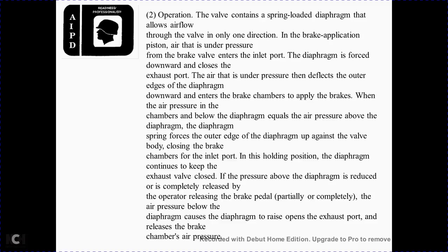Brake chamber to apply the brake. When the air pressure in the chamber below the diaphragm equals the air pressure above the diaphragm, the spring force on the outer edge of the diaphragm closes the valve with the body, closing the inlet port for the holding position. The diaphragm continues to keep the exhaust valve closed.